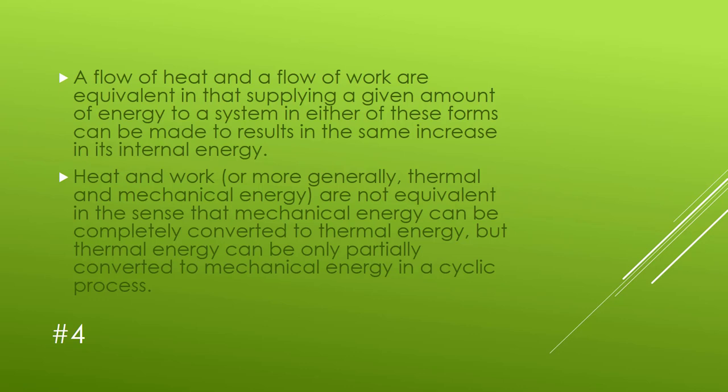The fourth is that a flow of heat and a flow of work are equivalent in that supplying a given amount of energy to a system in either of these forms can be made to result in the same increase in its internal energy. Heat and work, or thermal energy and mechanical energy, are not equivalent in the sense that mechanical energy can be completely converted to thermal energy, but thermal energy can be only partially converted to mechanical energy in a cyclic process. We'll be taking advantage of this when we start looking at these cycles and thermal efficiencies.